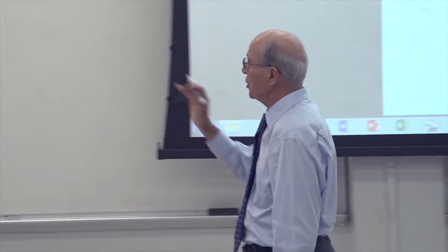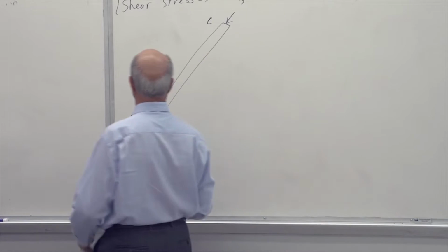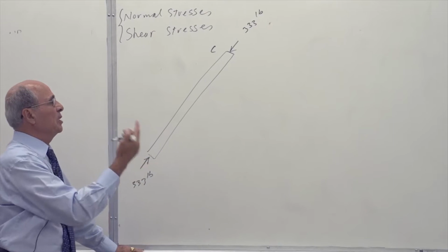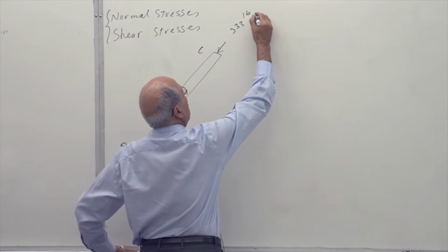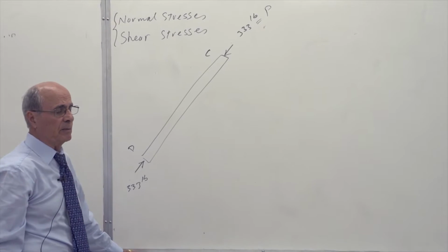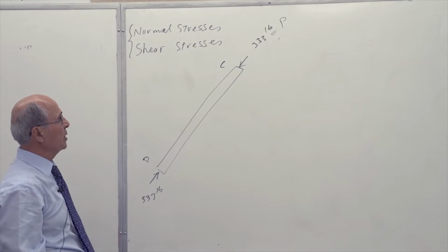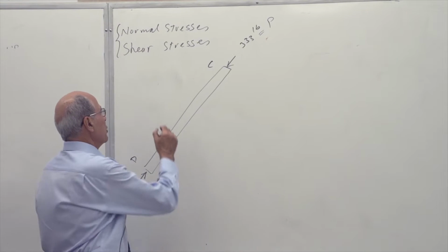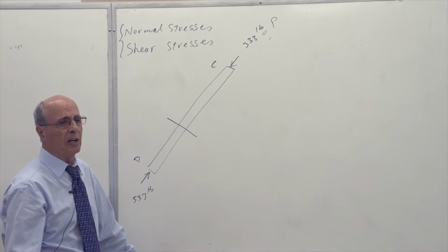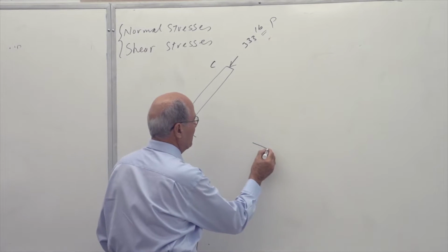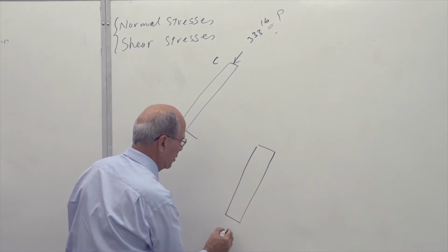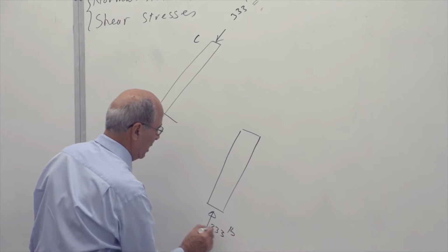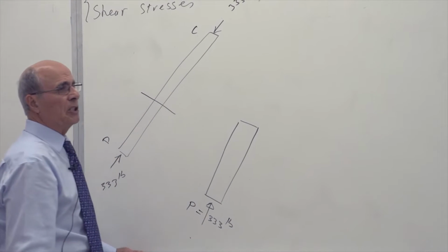Yeah? So it is in this format, which doesn't matter for the sake of discussion, that this rod could be under pure tension or pure compression. In this example, it was good. Now, we call this force P, which is the external force. That's how the lecture in your book is explained when you go through your reading. Then you make a cut here, somewhere, to find out what's going on. Then you draw the free body diagram of either the lower side or the upper side. This is the external load of 333 pounds.